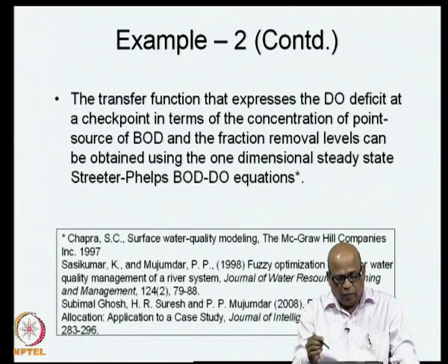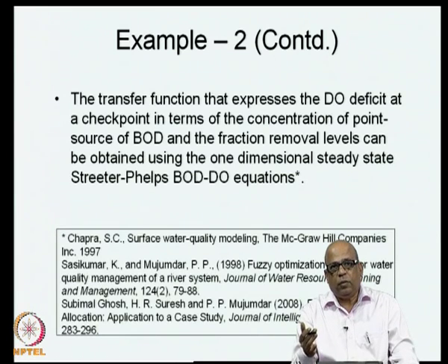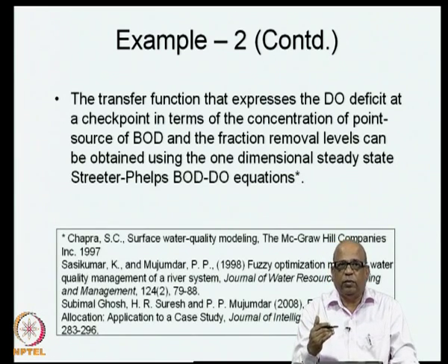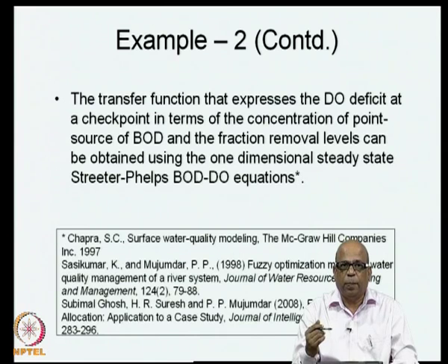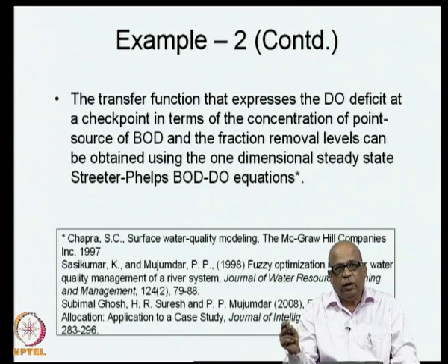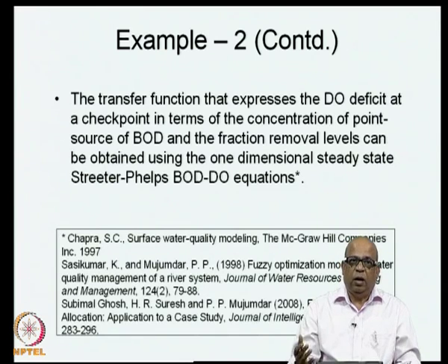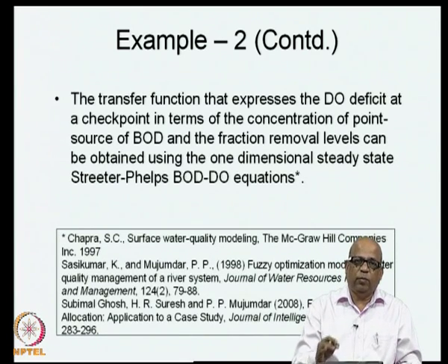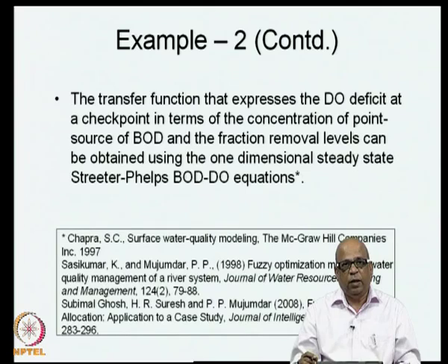Similarly, we will now specify the dischargers' preferences, or dischargers' membership function. As I said, the treatment level that you provide at a particular location for the particular discharger determines the water quality indicator concentration at a location L, and this is modeled by the Streeter-Phelps equation in this particular example.